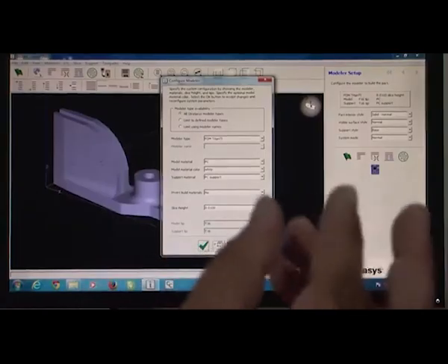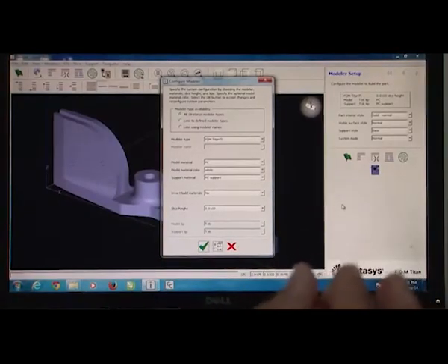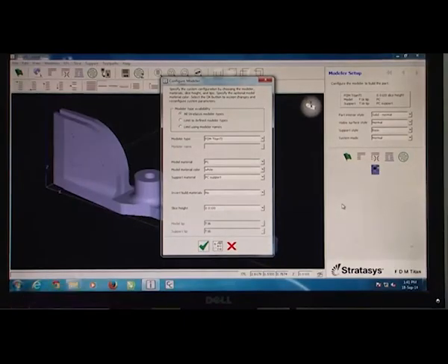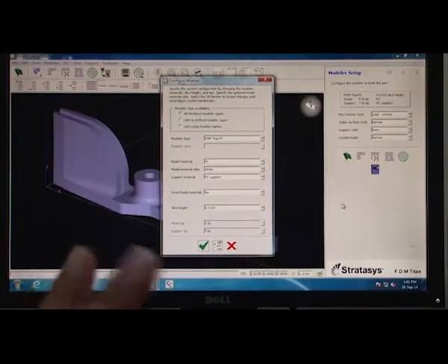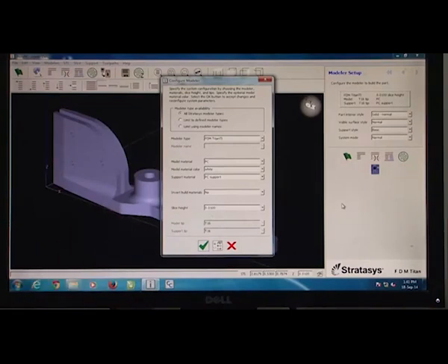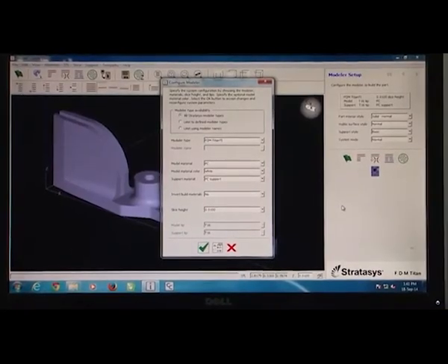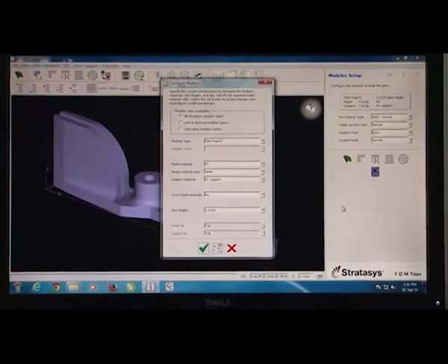So, if the nozzle is slightly higher in diameter, in that case the dispensing would be faster, and therefore it can go to a higher layer thickness. Okay. So, it all is defined by that layer thickness, that how the nozzle selection, etc., to take place. Typically there are 2 different materials, as I told you earlier, that this equipment can handle. One is polycarbonate, another is ABS plastic. So, when you are talking about ABS, there are different layer thicknesses even which are available. Okay. And all the nozzles, including T10, 12, 16 and 20, all the grades of the nozzles are being used in that category.